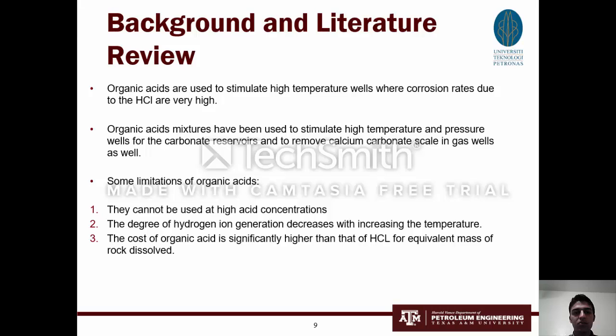Organic acids are used to stimulate high temperature wells where corrosion rates due to HCl are very high. Organic acid mixtures have been used to stimulate high temperature and pressure wells in carbonate reservoirs and to remove calcium carbonate scales in gas wells as well.